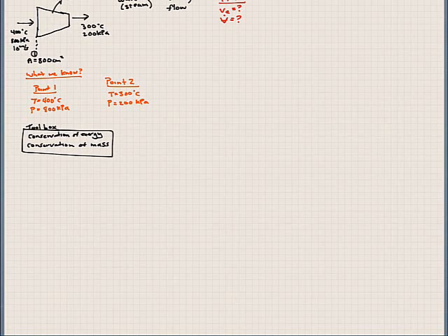Our conservation of energy is the first law. So we have Q dot minus W dot is equal to, for an open system, the mass flow rate times h exit minus h in. And since this is a nozzle, I'm going to go ahead and consider the kinetic energies also. So we have kinetic energy of the exit minus kinetic energy of the inlet. Well, there's not any boundary work done here since it's a nozzle system, so we can cancel that term.